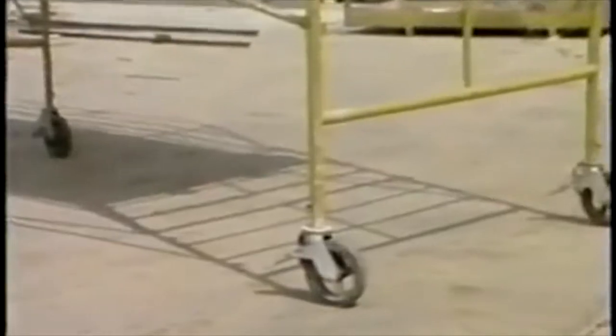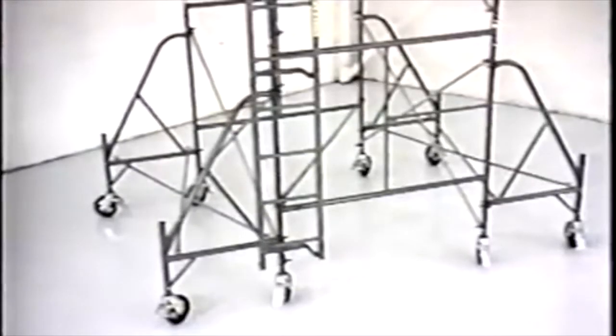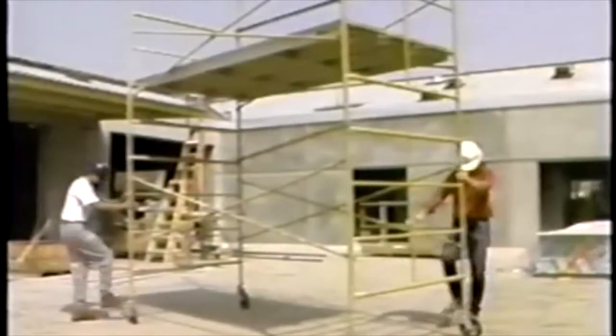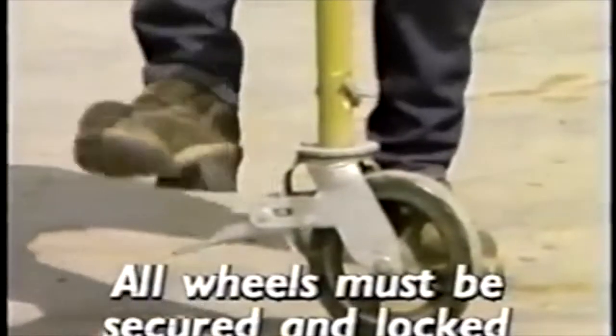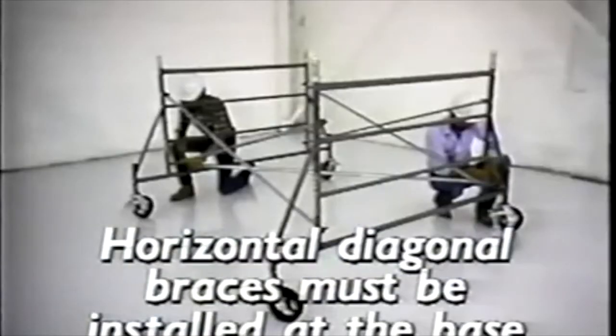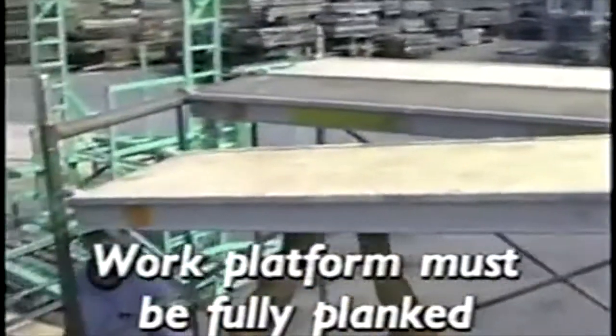Casters or wheels are attached for mobility. Outriggers, which are also equipped with wheels, can be added for additional stability. Prior to any personnel getting onto a mobile-type scaffold, all wheels must be secured and locked. Casters must be pinned to the scaffold leg or screw jack. Horizontal diagonal braces must be installed at the base, and the work platform must be fully planked.